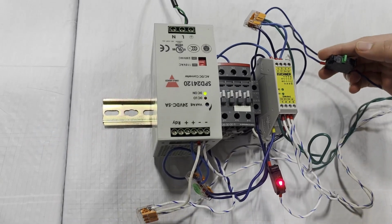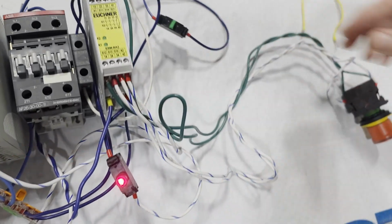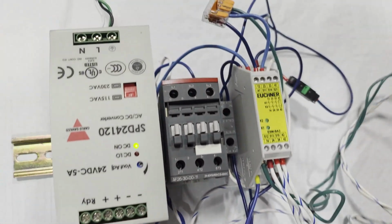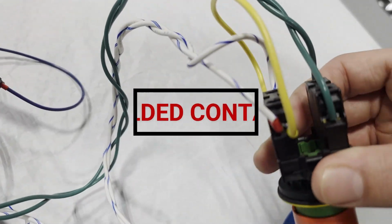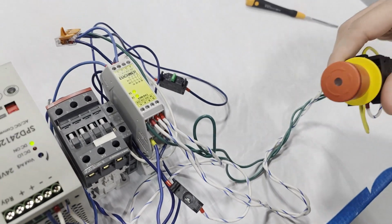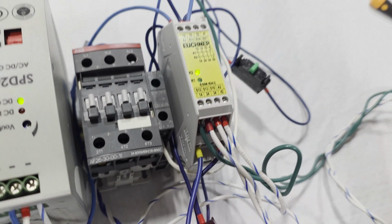Okay, e-stop pressed, it should not reset. Okay, so now we pull the e-stop out. So to simulate, we jumpered one of the contacts and our contactor is in. Okay, hit the e-stop. So that brings our machine to a safe state.